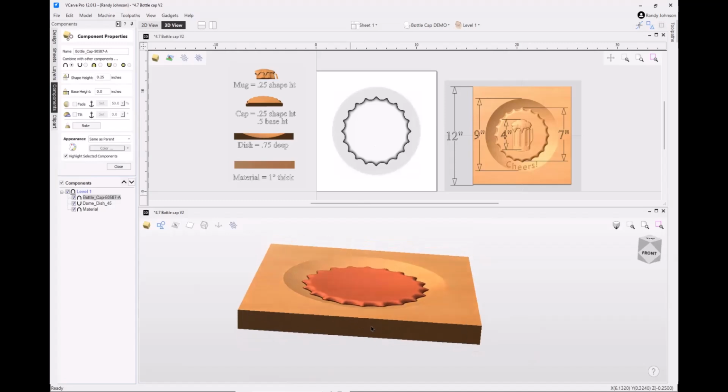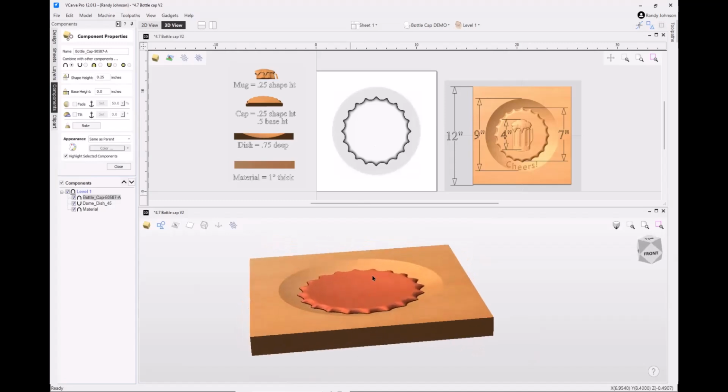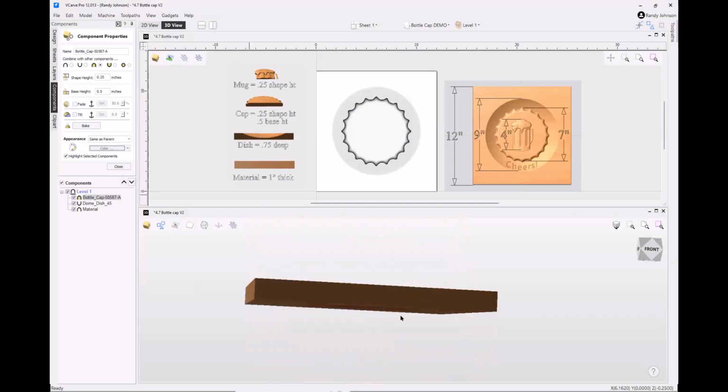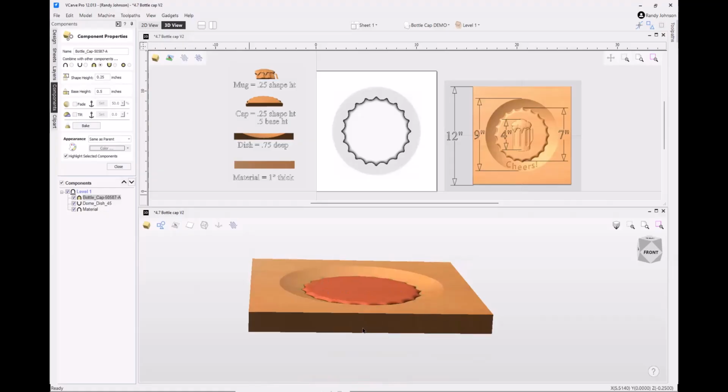Since I don't want the top of this cap to be curved, I want to put this on merge, and that will maintain the original shape of it, but it's hiding inside. So just like I talked about walking into the water, you go into the water that's too deep and your head goes underwater. We want to give this some foundation, kind of like standing on stilts in deep water. And if I add this foundation or this base height, it will then poke up that bottle cap up through that surface, and the bottle cap is flat on the top now.